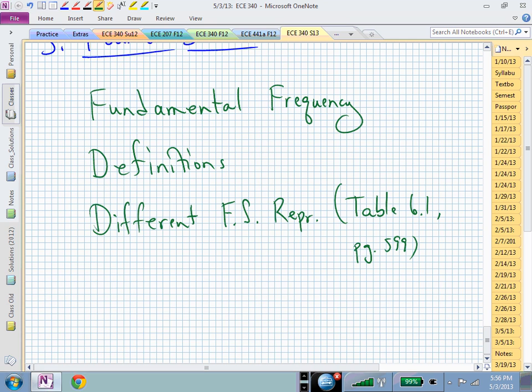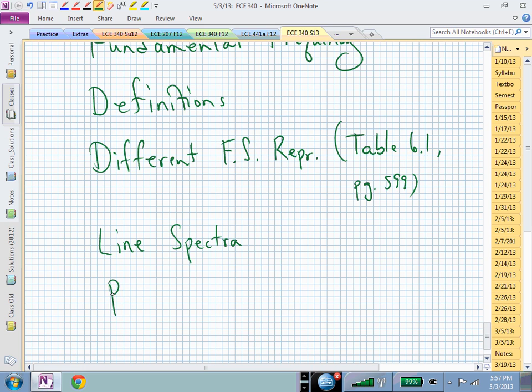The Fourier series gives you a little different frequency content. Now you're simply looking at discrete frequencies, the fundamental and the harmonics, meaning you now are looking at these line spectra. And I might ask you to find the power in some frequency interval by means of Parseval's theorem.